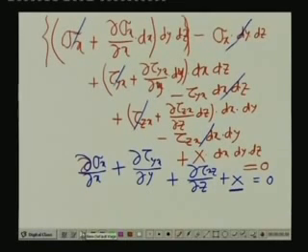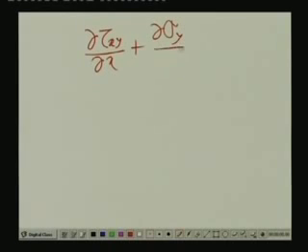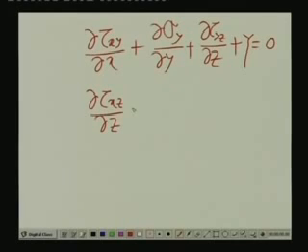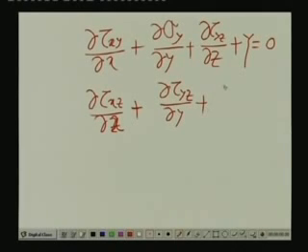Likewise, if we take the equilibrium of the forces which are acting in the y and z direction, we get another two sets of equations, and they are del tau x y del x plus del sigma y del y plus del tau y z del z plus Y, the body force component, equals 0, and del tau x z del x, I am sorry, del x plus del tau y z del y plus del sigma z del z plus Z, this is equal to 0.